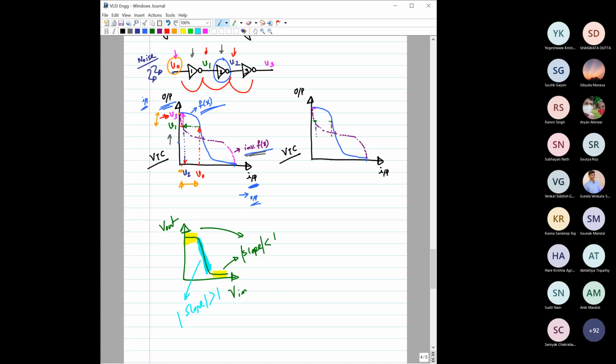If you see, V3 is now quite close to this VDD only, the highest level, the supply level. Again, that also depends on the characteristics of your VTC, meaning the slope and curve here. You can understand from here that it is going to reflect.